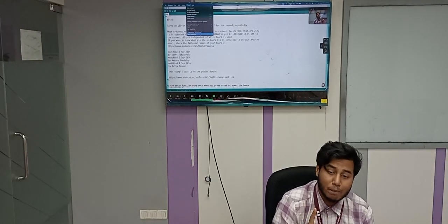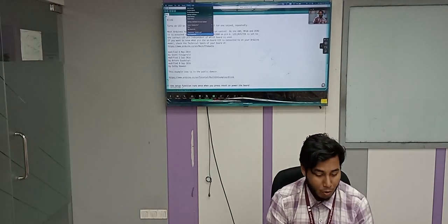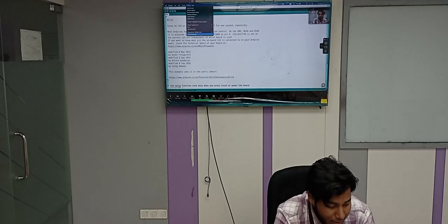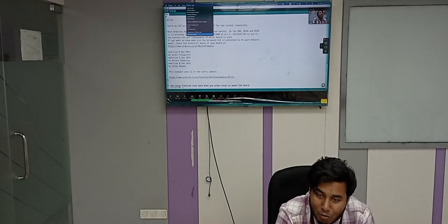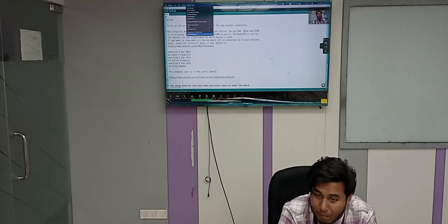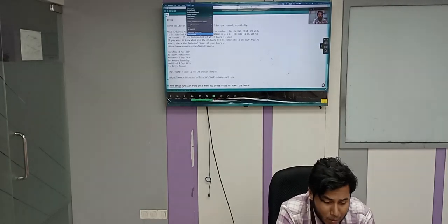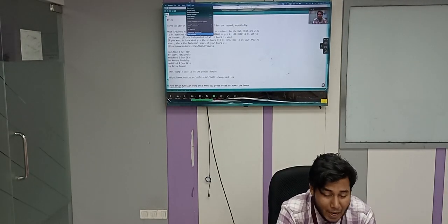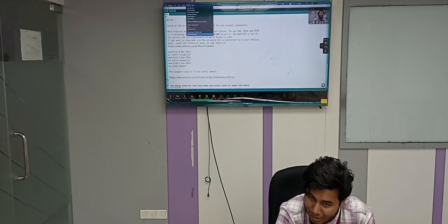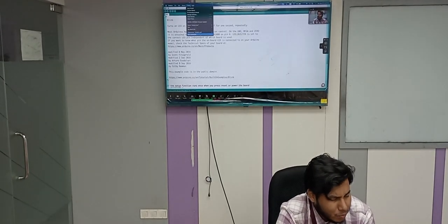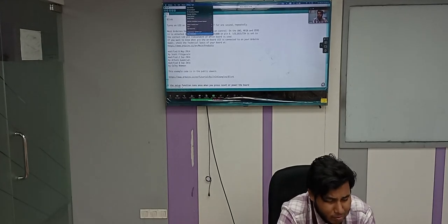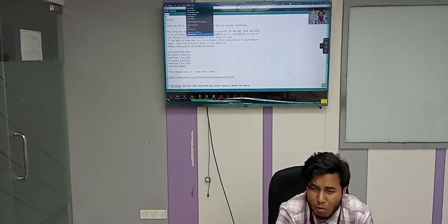Whenever you are going to use any programmable ISP, like you have only an MCU ATmega328P and you have to upload the code, then you have to burn that bootloader. So you have to burn that bootloader with the help of a programmable ISP, and there would be some manually designed circuit board where there should be an attached oscillator, ceramic capacitors, some resistors, a regulator or something else, or more than that.